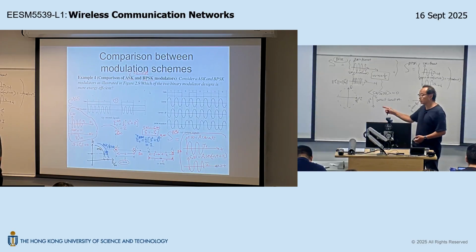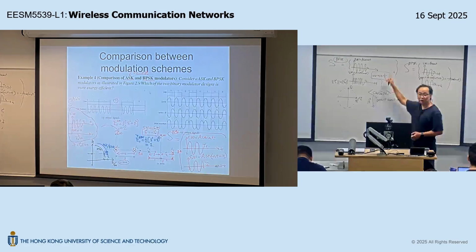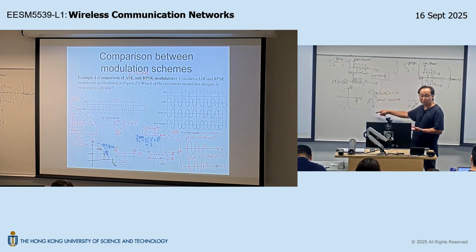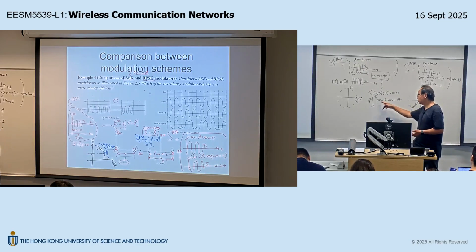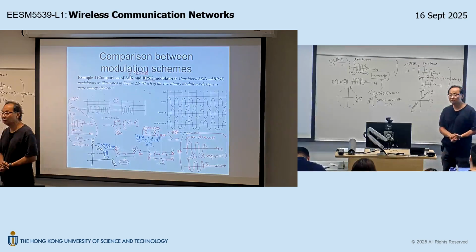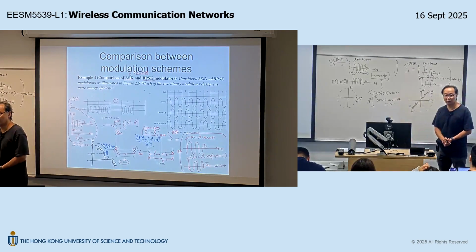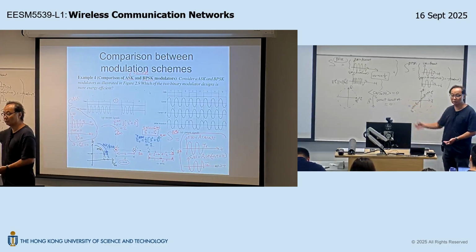Cosine (A minus B) involves the difference between these two frequencies. By this constraint, this difference will be an integer multiple of the base frequency, so you integrate over one period and that cosine (A minus B) term will be 0. Cosine (A plus B), similarly, you are integrating over multiple periods of a sinusoidal wave, so the average or DC level will be 0. Because of that, this turns out to be 0. You can try this offline using simple integration.